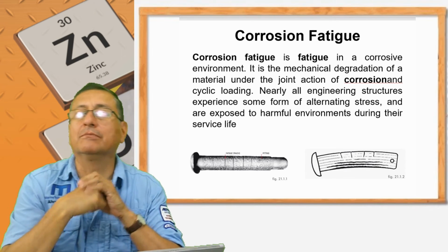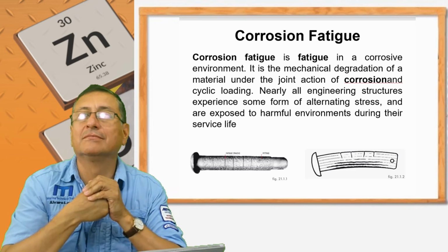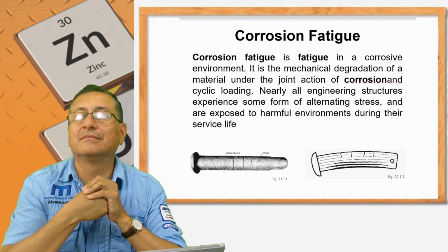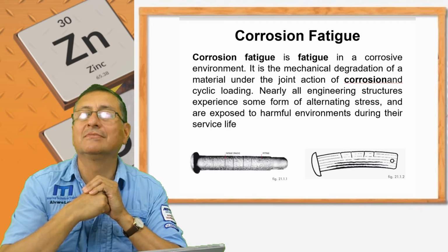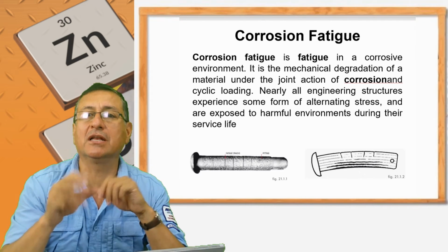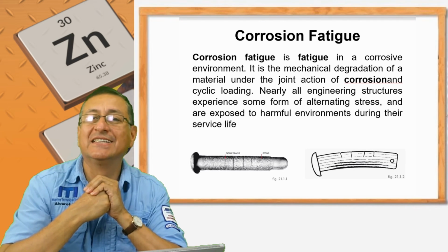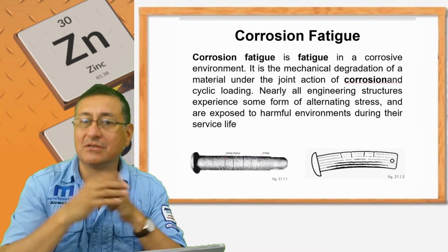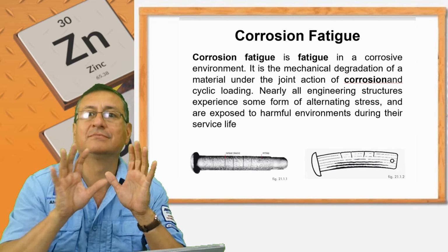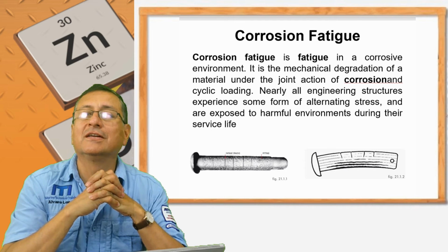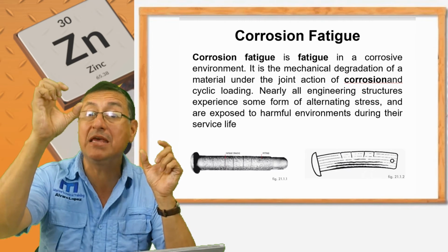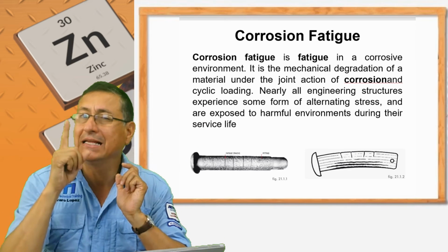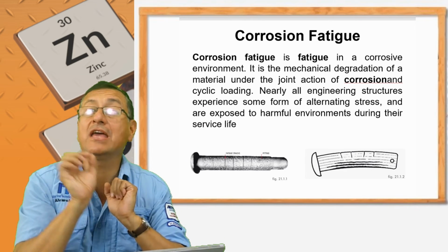Keep your boat clean. Number 1. Select appropriate materials. Number 2. Connect everything to the bonding. Number 3. Install anodes in appropriate parts. Number 4. And install good gauges and meters, especially digital ammeters, to verify if you have leaks.